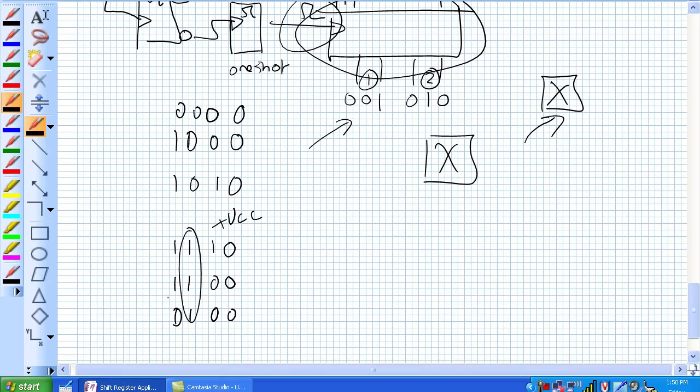Another thing to keep in mind is, remember, your active low loads, is it constantly high? If you're not loading anything at all, you would be in a +5 situation. Or maybe you're constantly loading something, you've got a short to ground. So keep in mind about that.